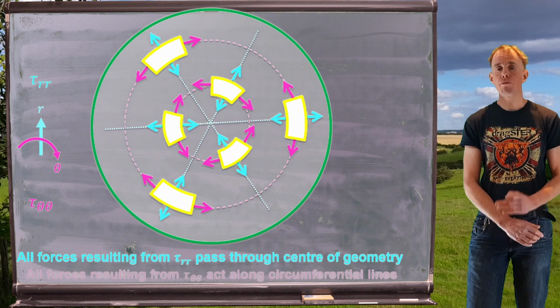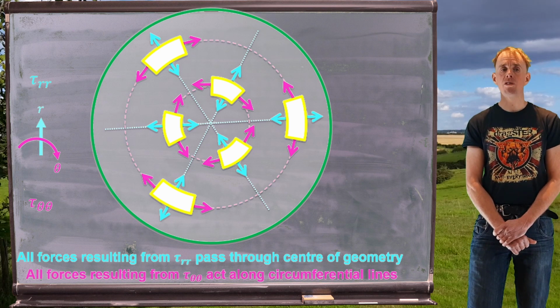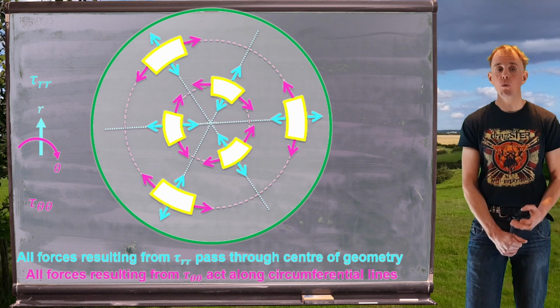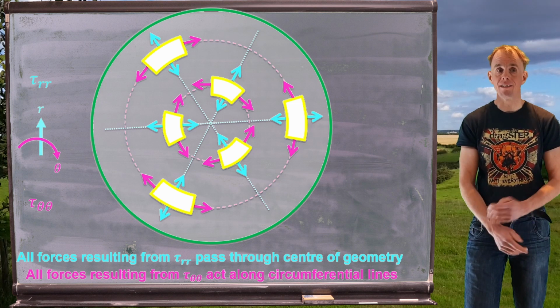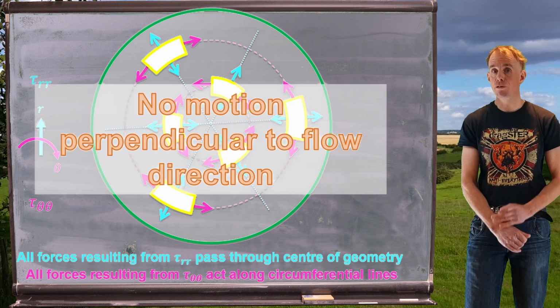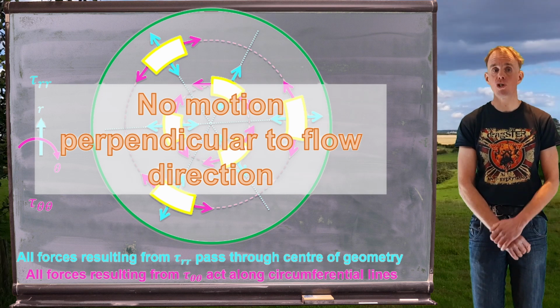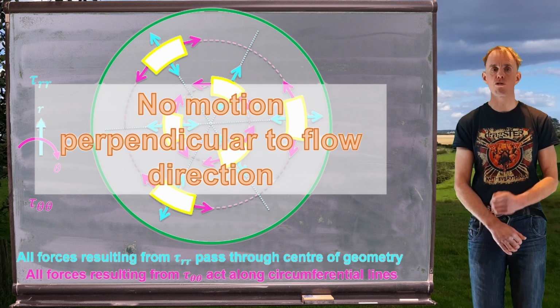So we can see that for a pipe, for a circular duct, all the forces that act radially pass through the centre of the geometry, and all the forces acting circumferentially act along these circumferential lines and cancel each other out, which means that for a circular duct there is no net force, there is no motion perpendicular to flow direction that is caused by our second normal stress difference.